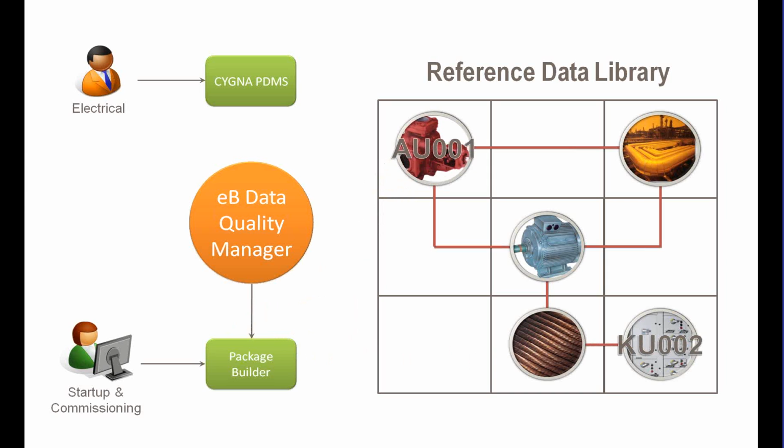But the advantage is that they don't have to assign codes to everything. They just have to assign codes to specific equipment types because of the relationships apparent in the system, where we can automate assignments to process lines. We can automate assignments based on the ontology, based on the relationships. Let's say you can assign the pump, and then we know that the pump, through data relationships, is associated to the motor, and we can automate the assignment of the motor.